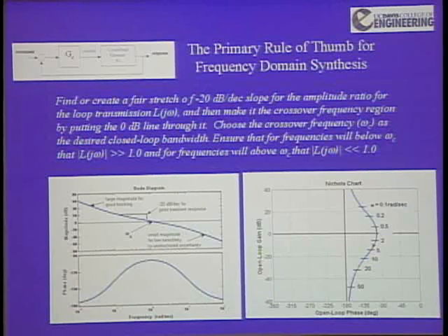So the human operator, the human pilot, is adopting, creating his or her own transfer function that obeys that law, the same thing that a designer would do for an inanimate control system. So there it is, there's the open loop Bode diagram. You do see this phase roll off here. This is the same thing on a Nichols chart. Okay, so that's kind of interesting.